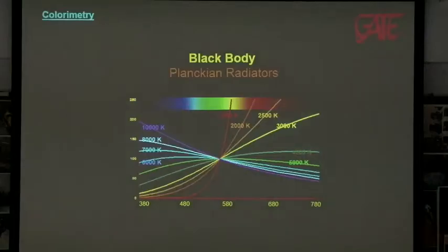So this is indicated by the Kelvin degree temperature. Therefore, any tube light or tungsten lamp you buy, they write the color temperature there. It doesn't mean it becomes that hot, but the color of the light coming from that particular tube or bulb is equal to a black body when it is heated up to that temperature. So the spectrum of the light given from that lamp is related to that. That's why it says the color temperature is so much. That means the light coming out has that particular color. You take out any tube or any bulb, you will find there is a color temperature there, right?